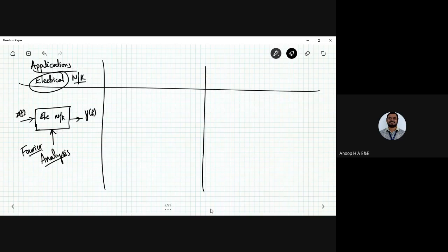So pulse width is being modulated using a sinusoidal wave and a triangular wave, and whatever the points that match. Okay, so the pulse width can be varied, like increased or decreased, depending on the triangular wave, that is the carrier wave there, right? So sinusoidal wave is taken as the reference, and by matching the points on the given sinusoidal and triangular wave, you are going to vary the pulse width there, right?